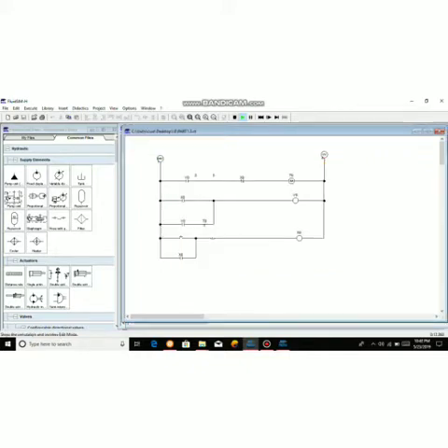Next, for circuit 4, we can get two operations. In the circuit, we use push button, contact, relay and timer. The timer is a component used to delay a certain operation. To activate the timer, the push button connected to the X0 relay is pressed as shown in figure 8. Then the timer starts and counts to 60 seconds. After 60 seconds, contact T0 will be activated and break the circuit, and it will return to the initial state of the circuit as shown in figure 7.